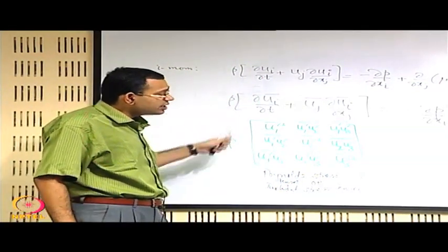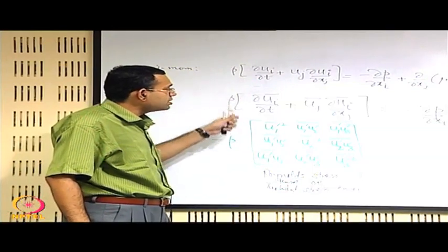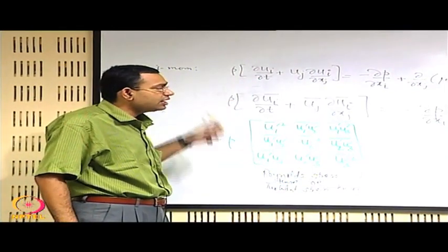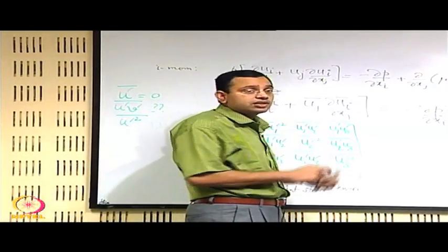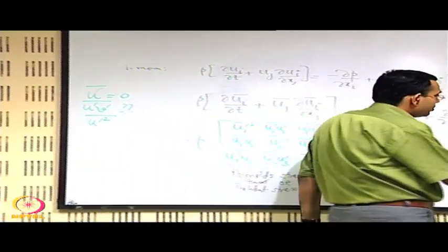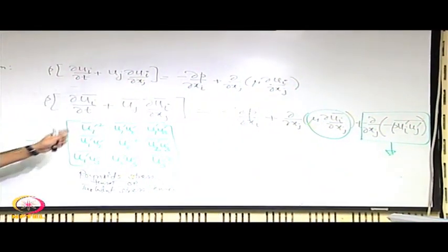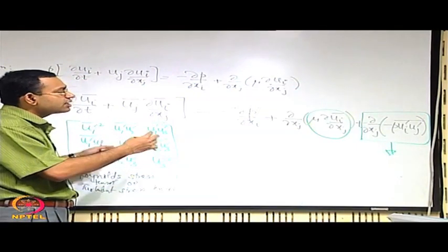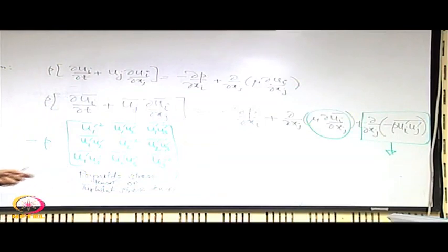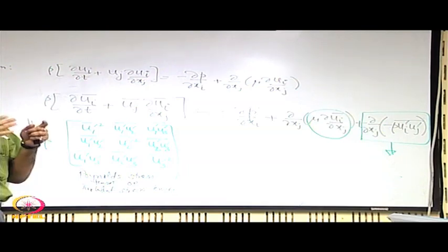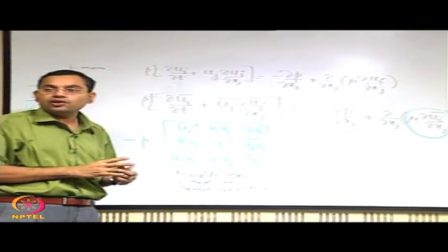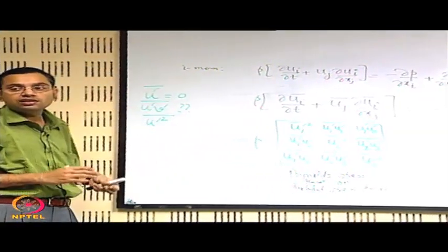Now, we have new sets of equations where the variables are very much deterministic, the statistically average ones, but the equations are not closed because you have now come up with many new unknowns through this term. So, you have 6 extra unknowns, and there is no magical way by which you can have 6 extra equations for these 6 unknowns. Of course, you may try to write 6 extra equations, but that might give rise to another new set of unknowns. So, closing the number of equations with the number of unknowns is one of the very toughest things in statistical averaging.